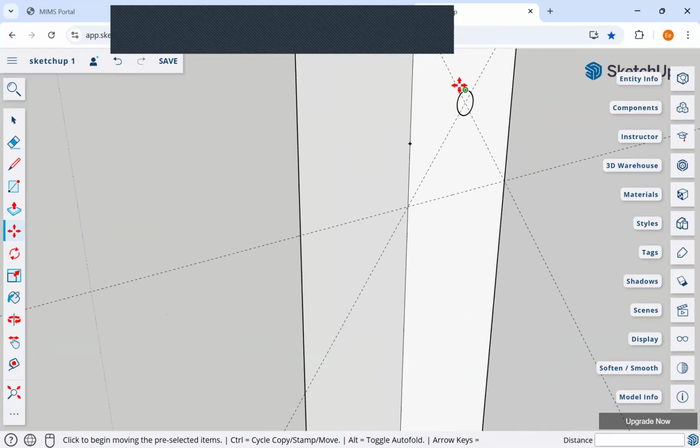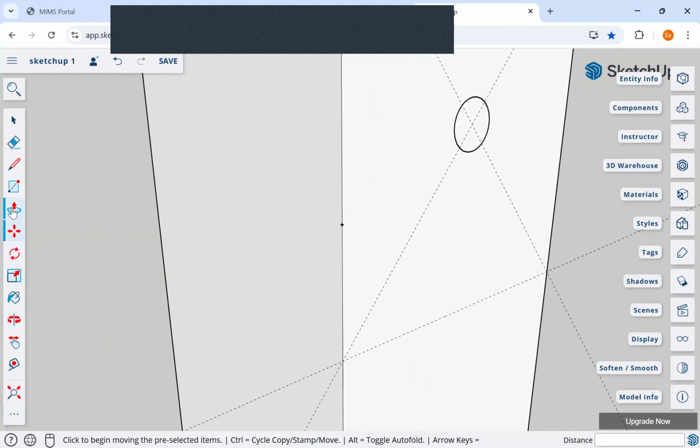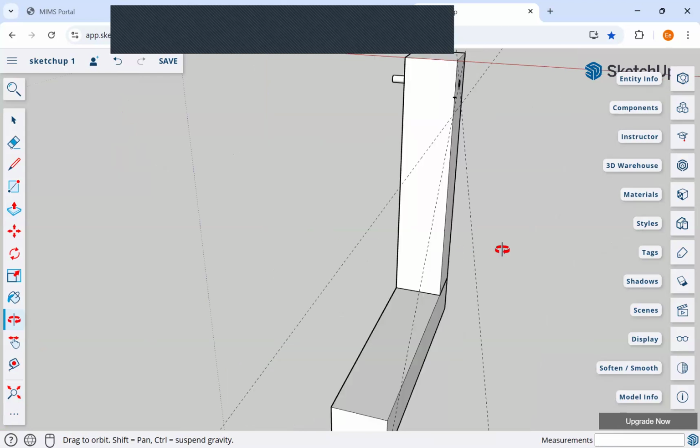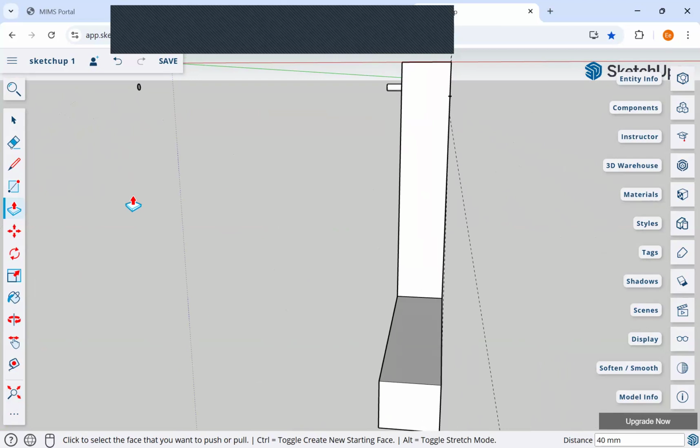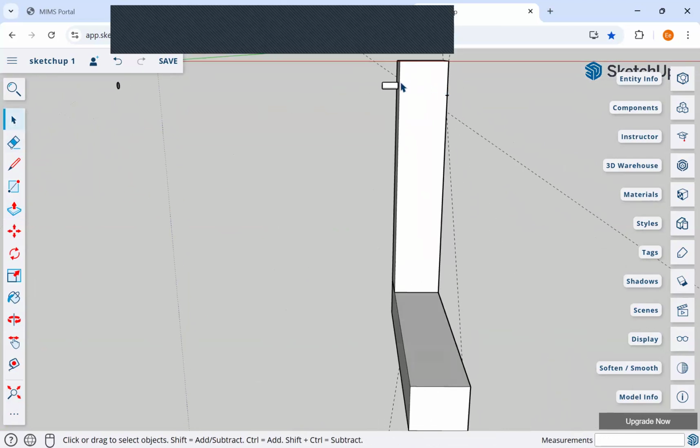So now what I do is this, zoom into here, go together, push pull tool. Okay, surface is highlighted. Must make sure that the surface is highlighted. Basically, it tells you that this is the surface you want to push pull. So I click on this, I'll pull in, and I key 40, and I press enter. Wrong, 40, enter. Okay. So now zoom extend again, and orbit it. Notice I've drawn a rod that is 40 mm long. Why 40 mm long? Because this is 10 mm, this is 30 mm. And we actually draw a hole 10 mm deep.